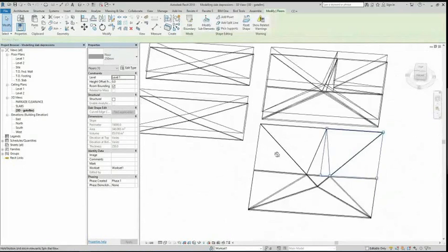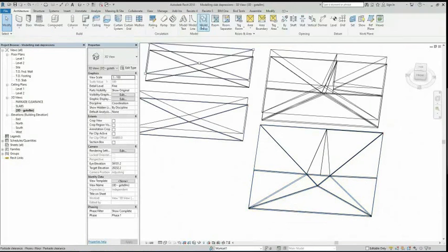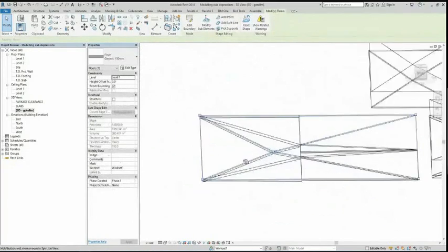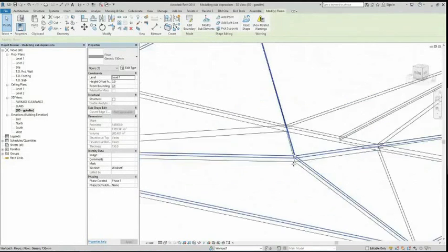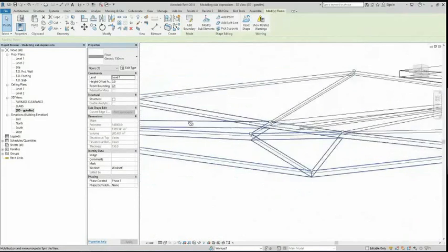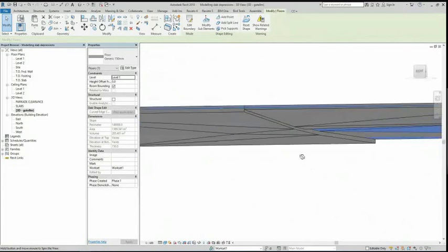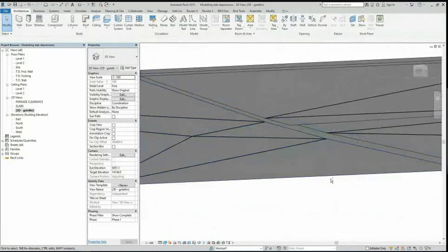So what I'm going to do now that I'm done making all these three separate floors depressed to this one area drain location here, I'm going to delete the sacrificial slab element, hence the name sacrificial. So you'll see that everything now lines up because you have wireframe to verify that. So the top surface of the slab all lines up with this, how it should be in a parkade or whatever area this is. But on the underside, I'm going to actually switch to a different view so you can see that better. All the different slab thicknesses now, for all the same profile, but you at least have those different thicknesses represented.